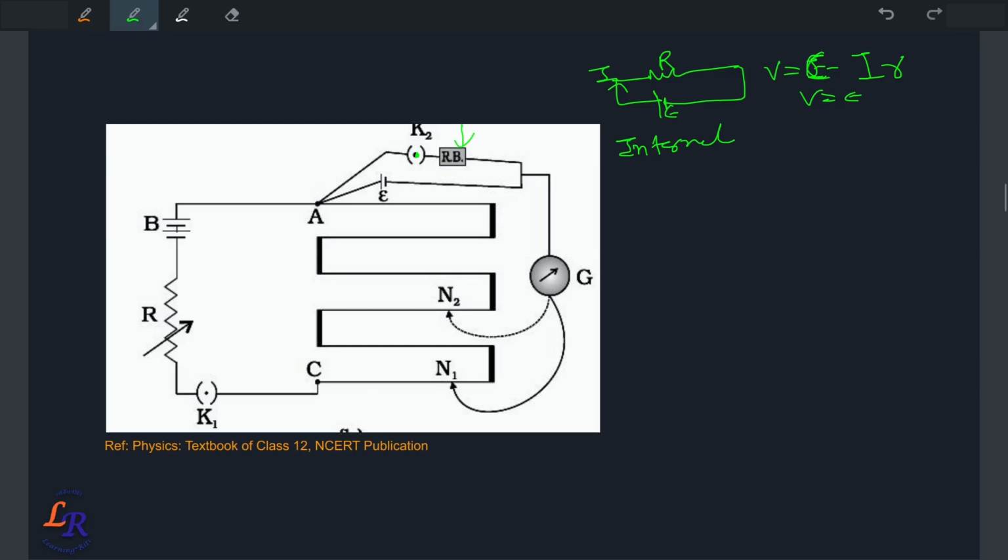So here again we utilize the similar concept, and the potentiometer would have this arrangement as it is. Once you connect this circuit, again you utilize the Kirchhoff rule, the summation rule, the loop rule here. So let's say in the beginning you have this epsilon connected in series, and this circuit will close, and this K2 is open, right? So the current will not flow from here, it will flow from here, and you apply this rule.